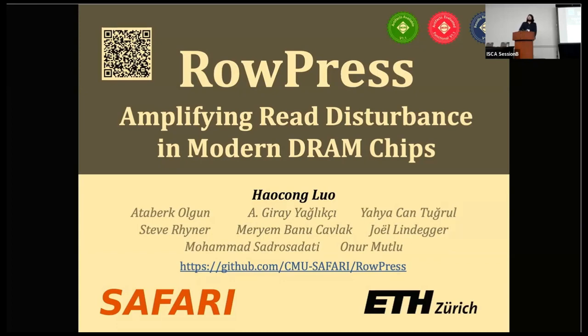Okay, and have you evaluated this in ECC-based DRAMs, like DRAMs with in-DRAM ECC? No, currently our infrastructure only supports GDDR4, but we are working on evaluating this effect in DRAMs with on-die ECC like GDDR5. So do you expect the severity to significantly reduce with in-DRAM ECC-based DRAMs? From the circuit level, we believe it might only get worse because the technology continues to scale down. But if we add the effect of the ECC, if we want to predict the bit flips with ECC, I'm afraid I cannot say before we finish all the experiments. Okay, thank you.